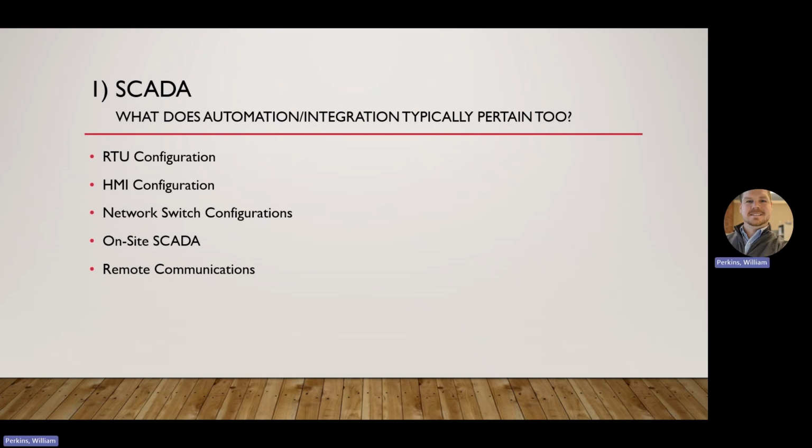And once local or on-site commissioning is complete, the SCADA engineer will also do remote commissioning, which is testing all the communications with the ECC. This will typically involve the SCADA engineer talking directly with the ECC representative and physically bringing in station alarms and analogs so the ECC can confirm all their remote data is accurate.